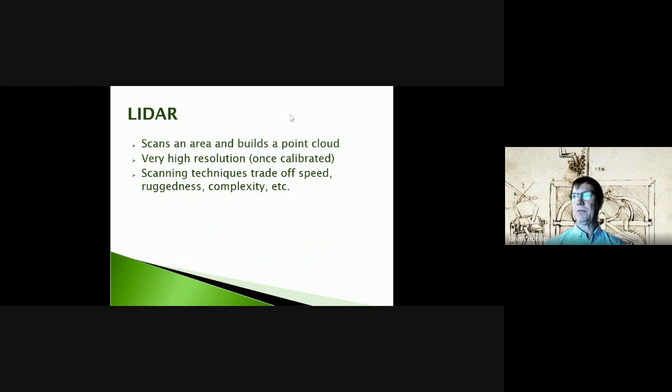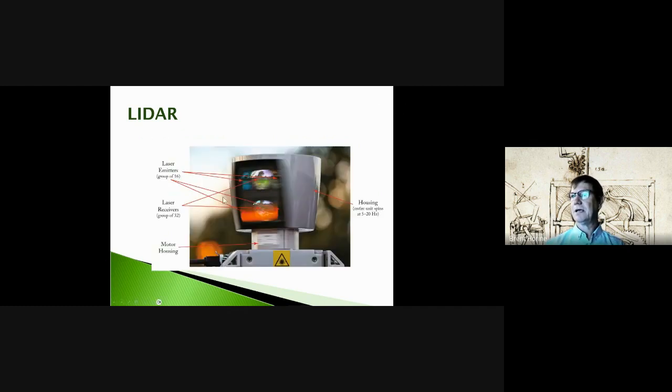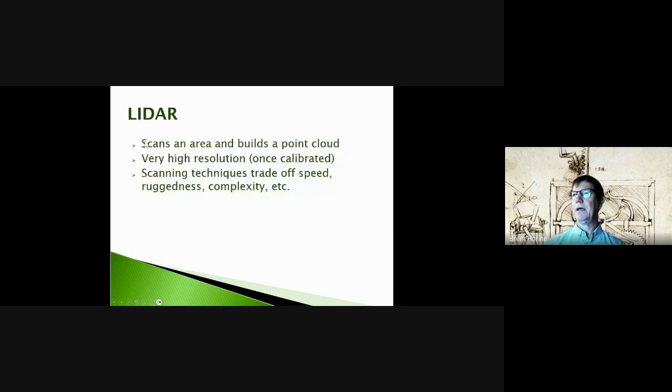So we need to encode the rotation of this housing and know precisely which direction it was heading. Then we take that 2D array, not just like what we looked at in the MIMO on the chirp radars, but analogous to it, and build up this point cloud in memory in our processing system.